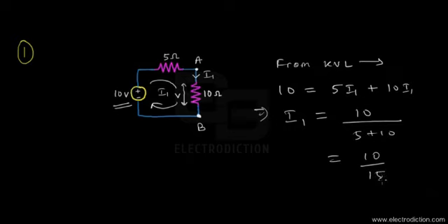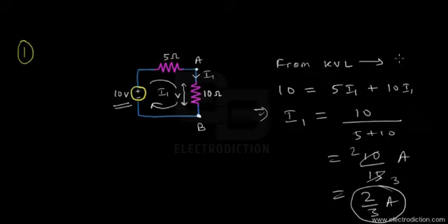This much ampere of current would pass through the 10 ohms resistor upon the inclusion of only the 10 volt source. We could find its value in decimal, but let's not go into those details. We can reduce it and make it 2/3 amps. That's better. So here we have the value of I1, which is of course 2/3 amps. Let's keep that in mind.